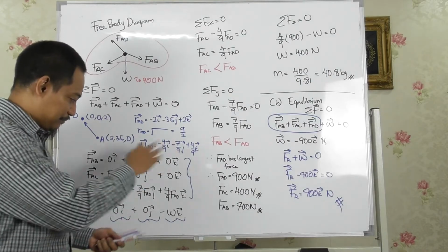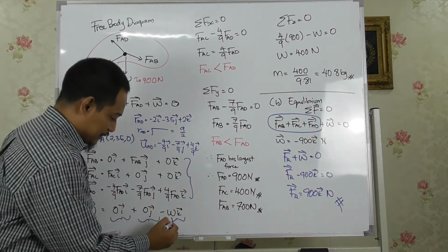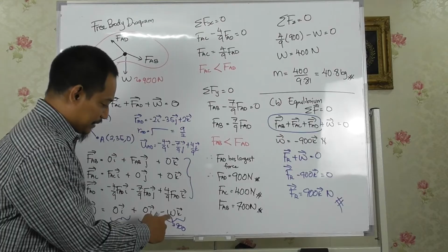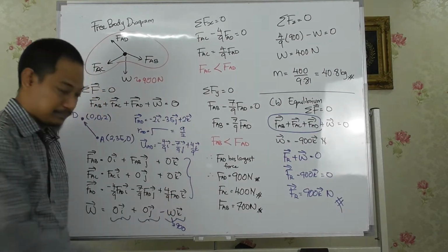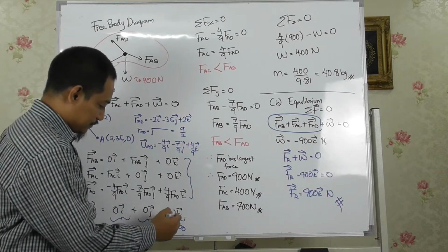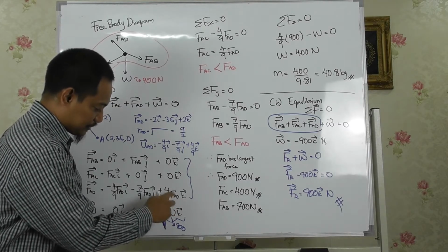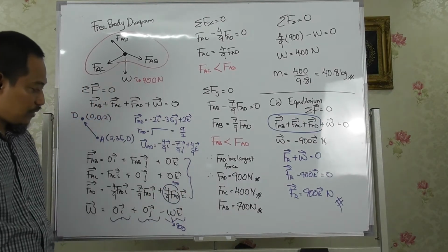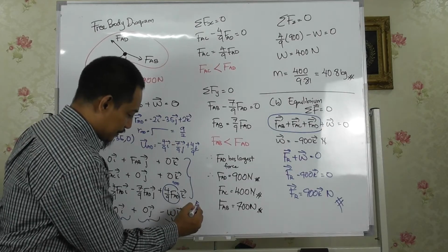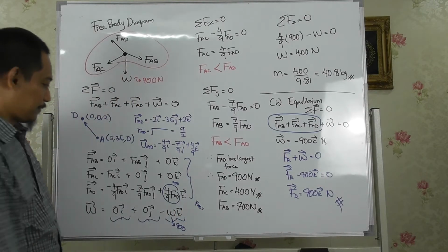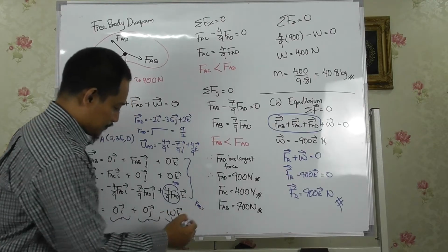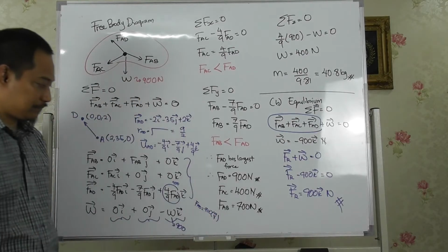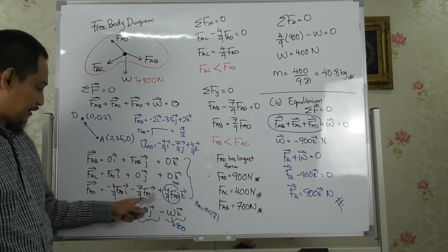Okay, if I'm to do it here, right? If this W is 900 Newton, right? This part B again. This is 900, meaning that the whole thing is 900, right? Sorry, because this is minus 900, so this one will come 900. So this whole thing is 900. Or in that case, FAD will be what? So it will be 900 times 9/4, right? That will be FAD.